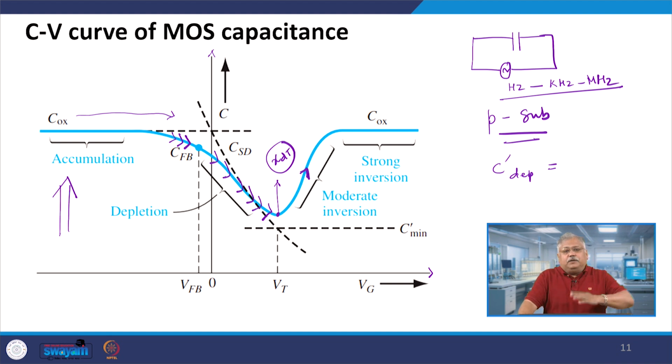Why is it rising? Because now the inversion layer is getting pulled up. So the minority charge carriers from the bottom and from the source drain region are getting pulled up, and the inversion layer is getting formed, and that is the reason your capacitance starts to rise, because more and more charges are being developed, free charge carriers. Then when your gate voltage reaches a substantially high value, you again reach the original value of Cox, right.